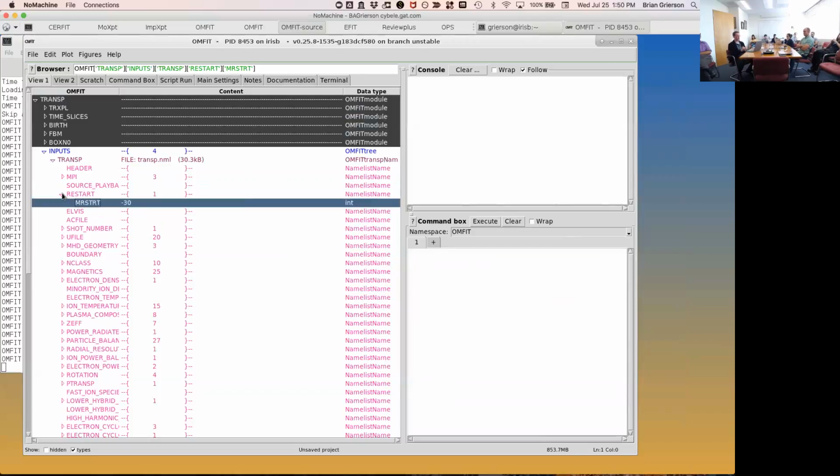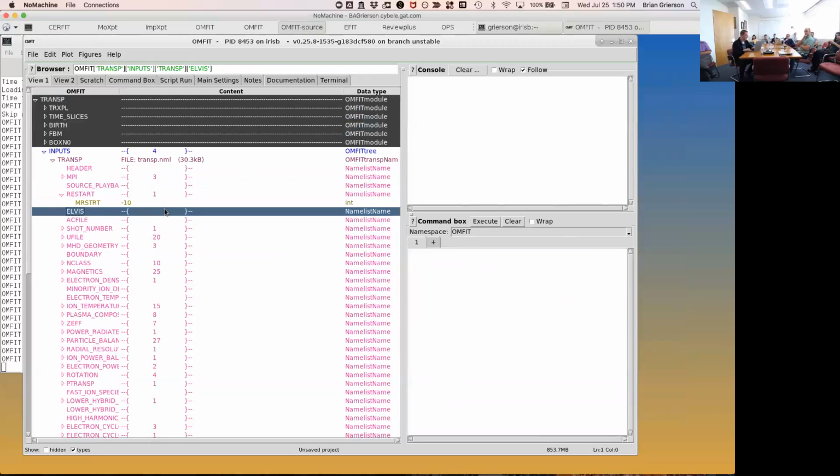So for beast mode, I don't want to take time writing restart data. If the run crashes halfway through, it's relatively inexpensive. I can submit another one. But if I want to make this a very important run, I want to write restarts in case of a failure more frequently. I can change this to 10 very easily.